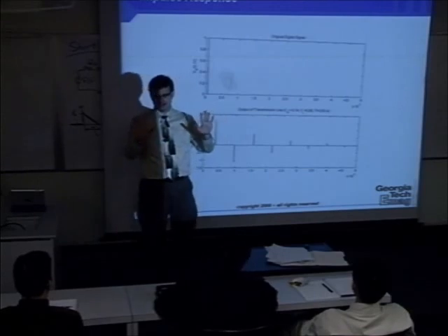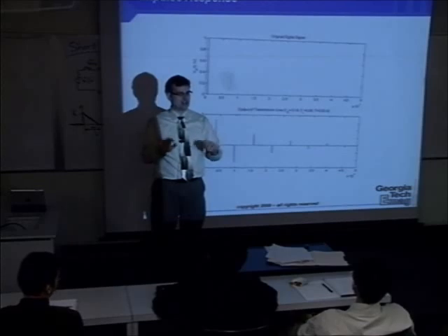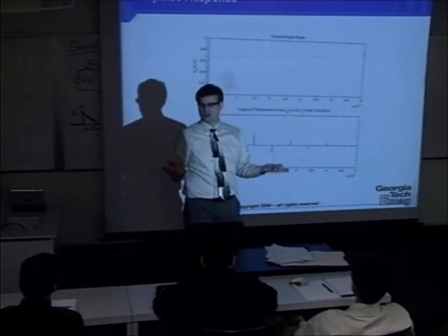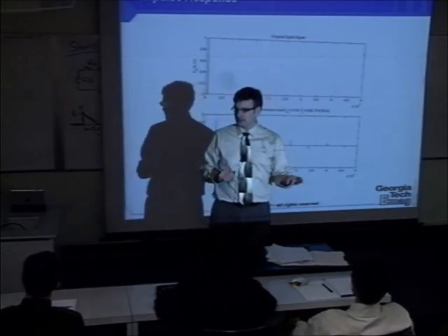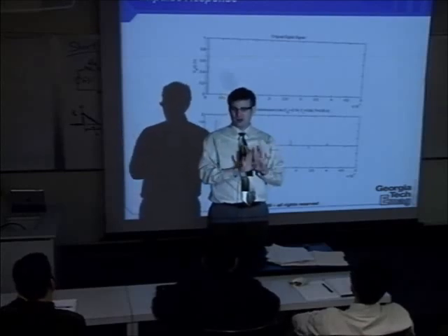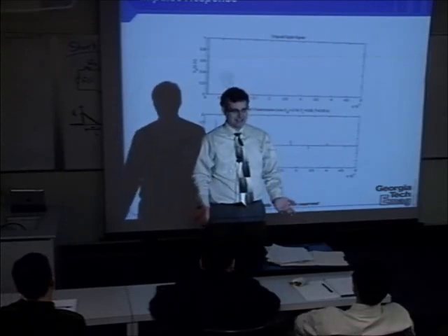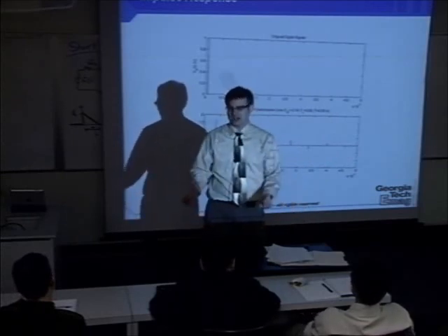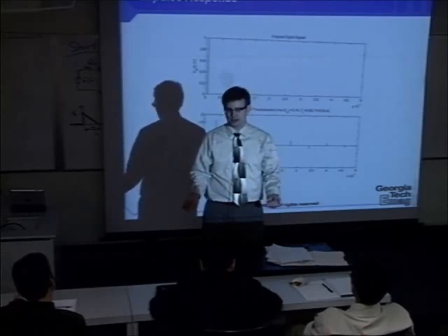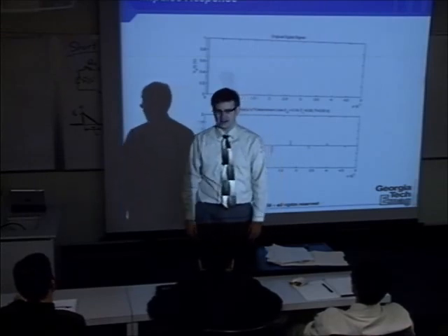That's right. Boy, did y'all do convolutions already? Yeah, I'm not going to ask you to do any more convolutions. The whole reason why we introduce convolutions is to make sure that you never do it again. Right? No, seriously. It's a very important concept. You got to fold this waveform into your impulse response to figure out what your output is. But nobody ever does that. We teach you what a pain it is in 2025. And then we teach you this trick. This trick is, you say, if you can make a Fourier transform, convolution becomes what? Multiplication. Oh, that's so much easier than convolution.